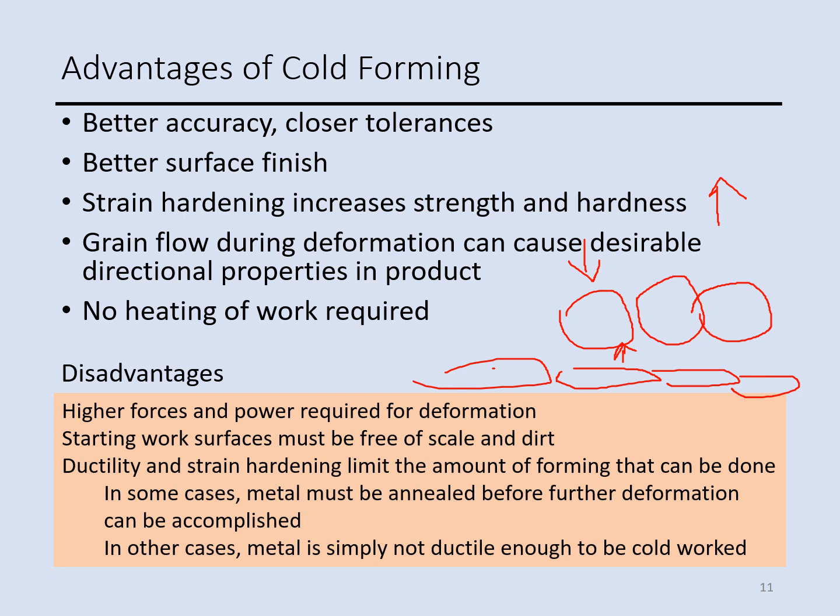If you want to have a higher strength in this direction, because these grain boundaries are closer to each other, the strength in that direction is going to be higher compared to this direction. So it might be favorable in some operations. Another good thing about this process is that we don't need any apparatus or equipment for heating, because we are performing the process at room temperature.